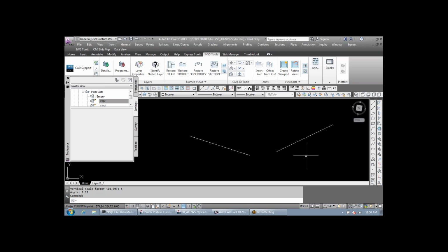The one thing I have to tell you about this is it has to be lines. It can't do polylines, which is kind of a bummer because if we do our pipes or trenches, it's usually one polyline that we like. Not that big of a deal. What I would suggest is explode your polyline real quick, run the LISP routine to figure out your angle, and then undo your explode command. So not too big of a deal, but this could be very helpful to you guys. Hopefully you'll get some use out of this.